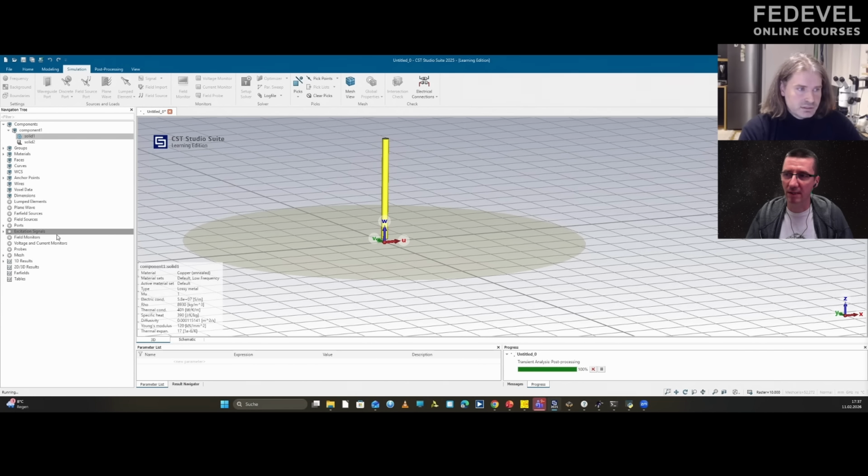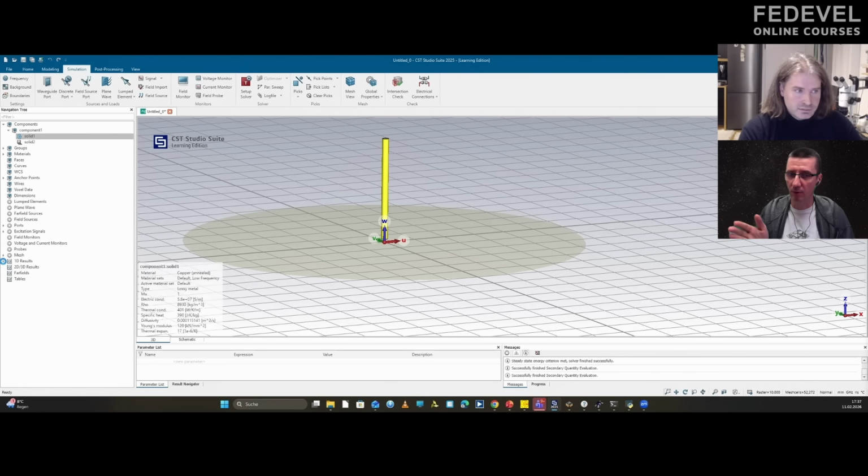So if we were, for example, importing the antenna which you have in your presentation, we would only need to import the L part and that's it? Yes, exactly. This would be enough. What I would use is DXF export. So I would make a DXF, and with DXF I can import in Altium, in KiCad, and make a proper design. And then you have to create also the ground plane, yeah? Correct. Yes, exactly. I need a clearance here for the ground plane.